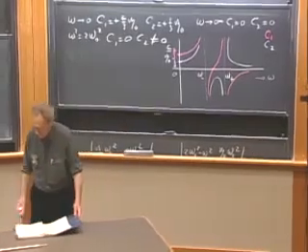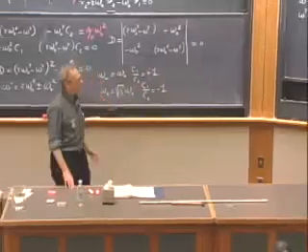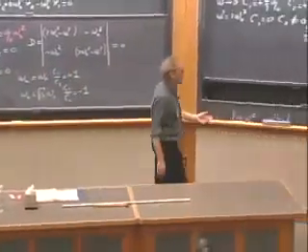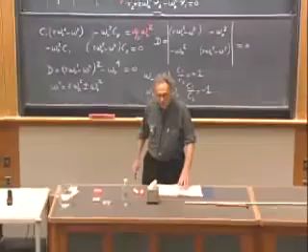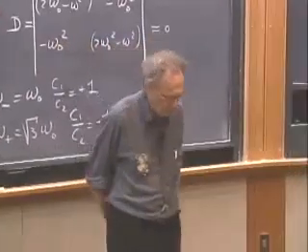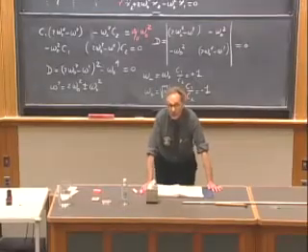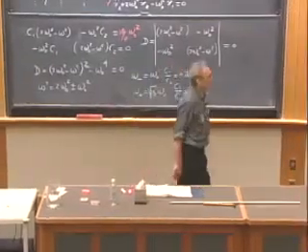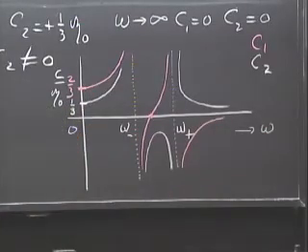Now we ignore damping, and because we ignore damping, we get these unphysical infinities when you hit the frequency omega minus and omega plus, these resonance frequencies. Now if you include damping, then the solutions become extremely complicated, but of course you avoid the infinity values, but the resonance amplitude can still be very high. And so these plots are still very useful provided that you don't interpret the infinities as being real, but something that is very large. If Q is high, then of course the amplitudes are enormously high. And this can lead to destruction.